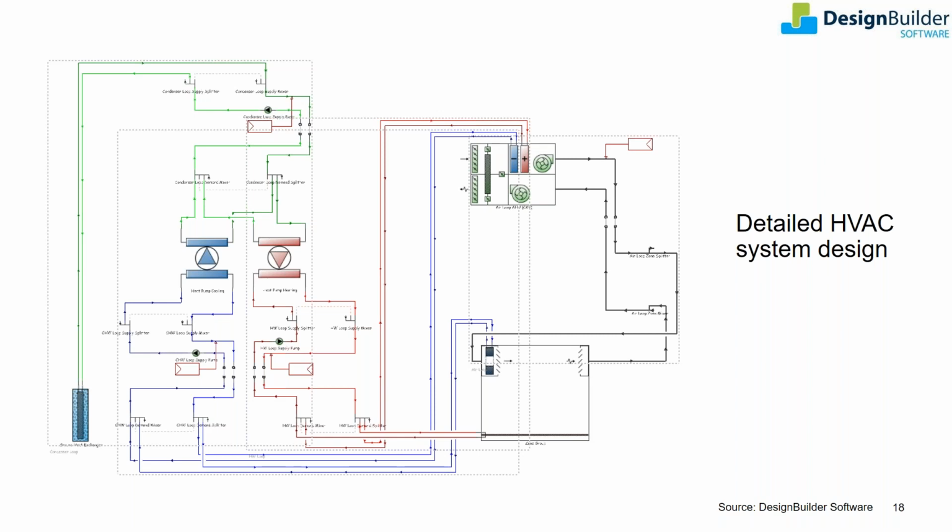In my opinion, this decision should be based on the stage of the building procurement at which the model is being created. If the modeling is being done at advanced stages of building procurement, when HVAC products being used are finalized, then at that stage, a proper system modeling might be helpful. In earlier stages of design, it could be avoided and taken up later, because time and cost involved might not be justified. In this case, I am not modeling a detailed system.